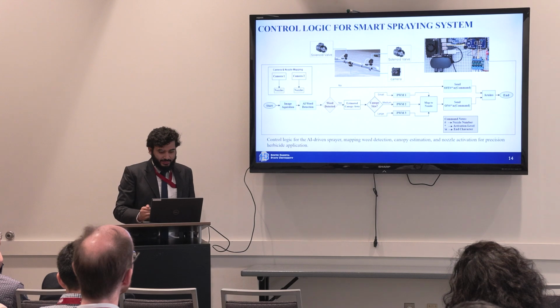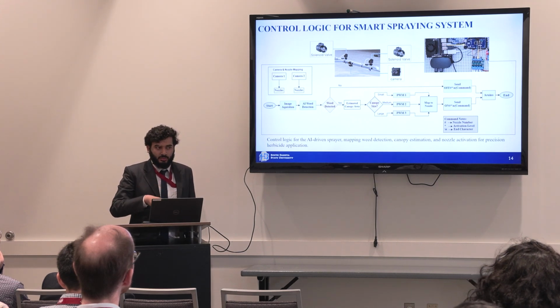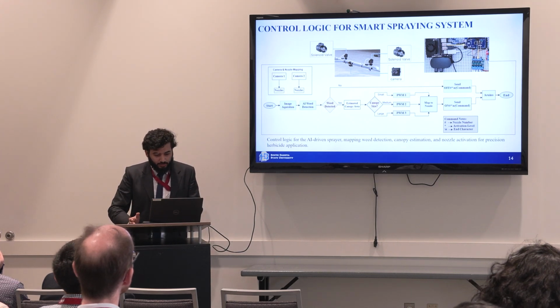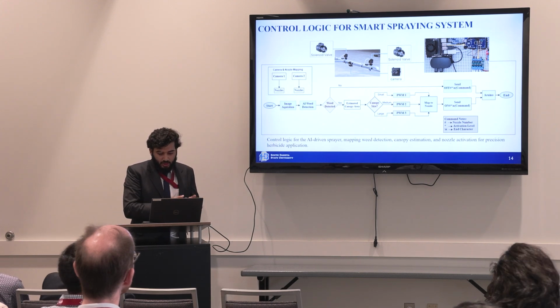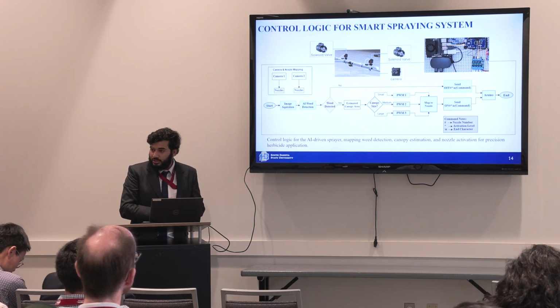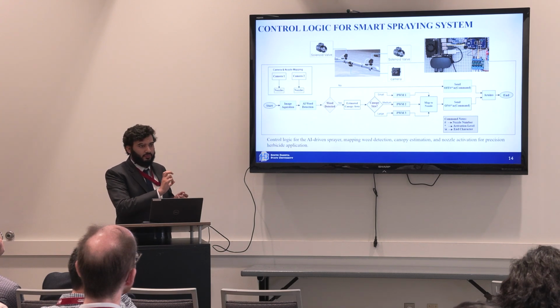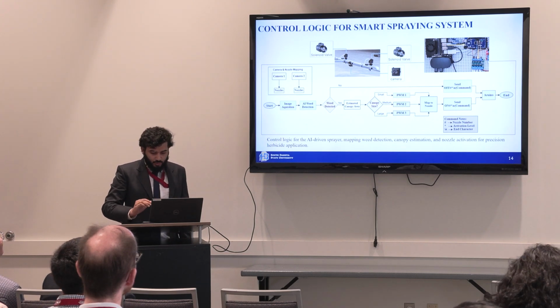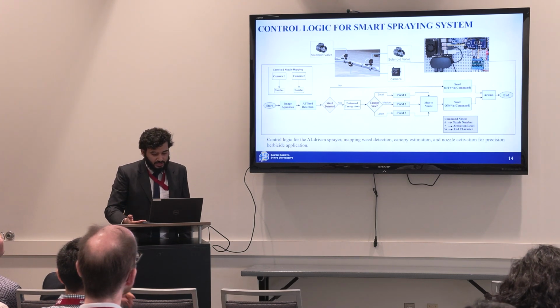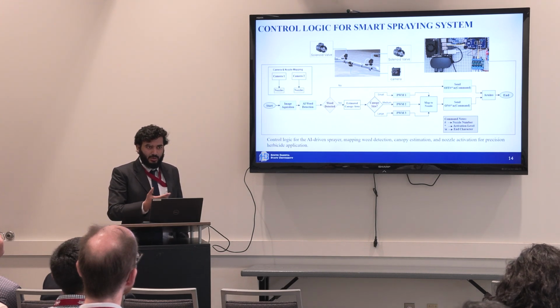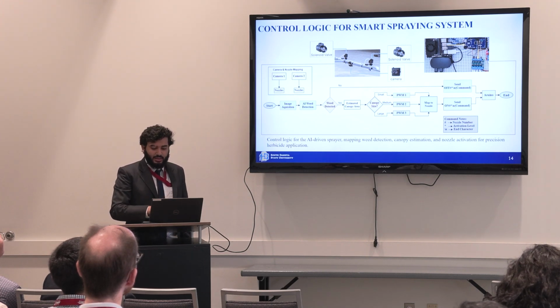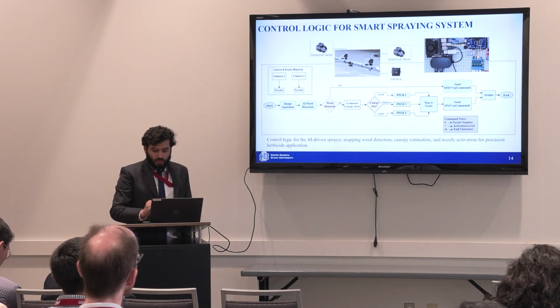But if we have a weed detection, then the cropped images pass through the canopy area estimation or segmentation model to see whether we have a small canopy area, medium canopy area, or large canopy area, to which we have a PWM value mapped, and then a message is sent as pound asterisk backslash n. Here pound means nozzle address and asterisk means the PWM level to apply there.